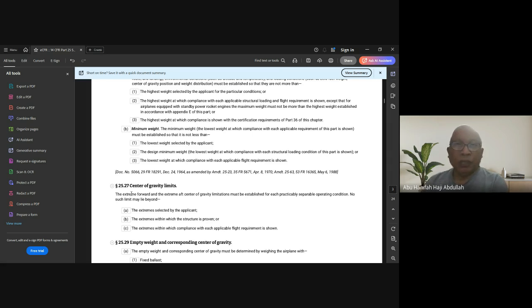The effect on the force will be the size, in this case the S. You have only limited size in your control surfaces, and limited size means you only have limited forces. That's why we need to establish the forces that are available in these control surfaces: what is the extreme forward and extreme aft. For helicopter, there's also lateral CG limitation. For the airplane, just forward and aft.